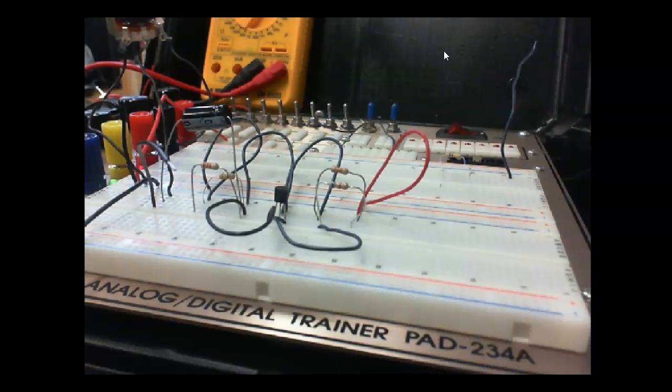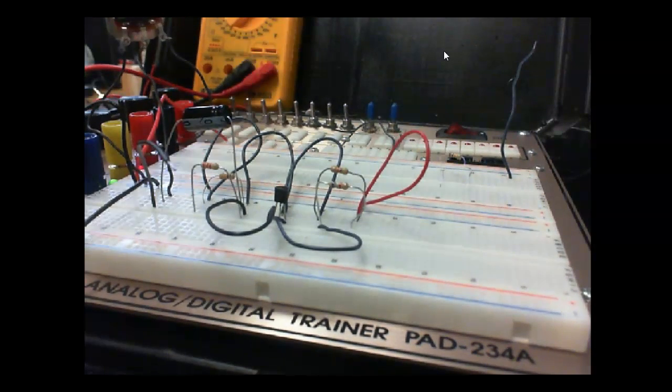What do you mean? We don't set the frequency on the scope. The scope measures it. I've seen people do that. I said, I want 5 kilohertz, and they're up there messing around with their scope. That's like saying I want 5 volts on a power supply, and I'm up here messing around with my volts per division on my meter, trying to get 5 volts. Well, these are test equipment. They measure what's there. Does that make sense?